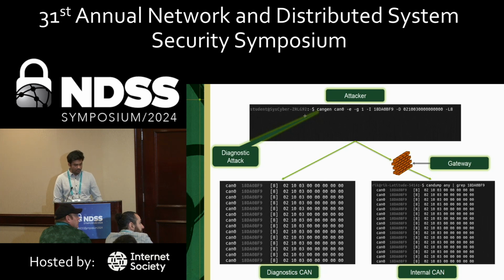However, by nature of design, diagnostic messages are allowed by the gateway and are not checked at all. They have to allow it for diagnostic purposes, otherwise vehicles won't run on the road and you cannot get your truck or car serviced, which is not something you want. So by design, this is a flaw, and this will be there. Gateways will have to allow diagnostic messages, and there is no throttling or sanitization for diagnostic messages being allowed into the internal network of vehicles, and this is what makes our attacks unique.